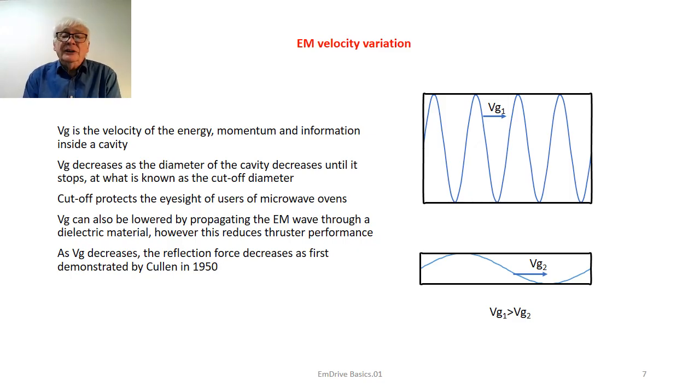As Vg1 is greater than Vg2, the guide wavelength at Vg1 is much less than the guide wavelength at Vg2. There are obviously equations which cover the calculation of both guide velocity and guide wavelength, and these are essential to the design of a tapered cavity, which we will cover in lecture 3, the design of a cavity.